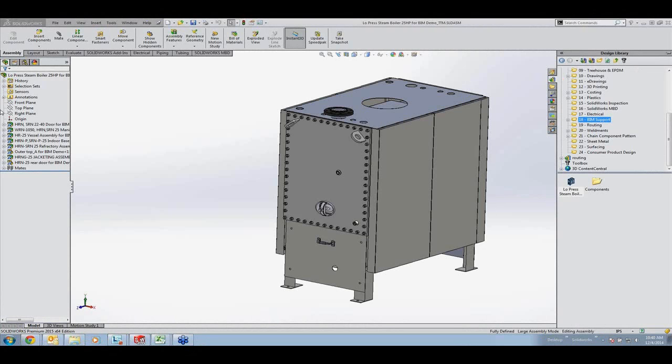That's crazy there, so I'm going to change the scale here to 1. All right, that looks better. I can also increase the density of the curvature combs. So you can easily see how the curvature of this face, not a very sharp angle here, but the curvature increases and then the curvature decreases. I can also show the zebra stripes here, which also demonstrate visually the curvature of the face.